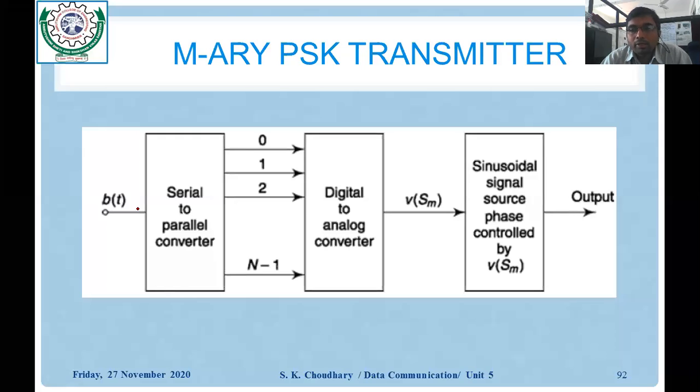We know that we are learning about the M-ary PSK, where we combine n number of bits to make a symbol. The first symbol has n number of bits. So this serial to parallel converter has the facility for sorting the n bit symbol, and these n bits are presented serially to this system, in a time sequence one after another.